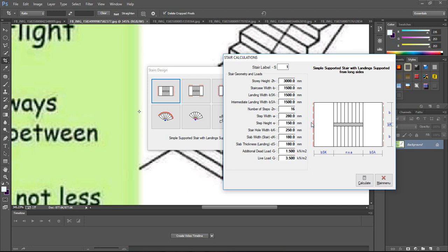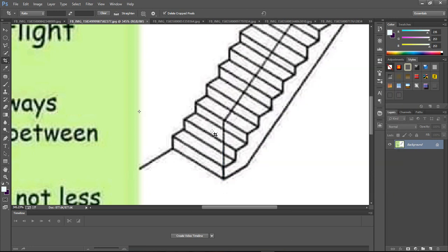That's for my own design. I don't know what you use for your design. That's what I choose for my design. That's your riser. Then the area. The area of a staircase is the place at which your foot will be laid, the place that you are going to climb. That is the width, the span of the staircase. That's your A in staircase design.